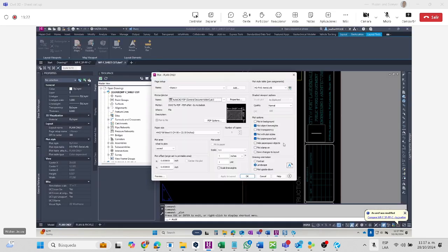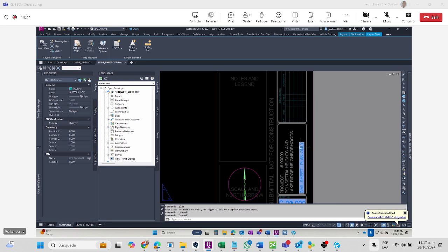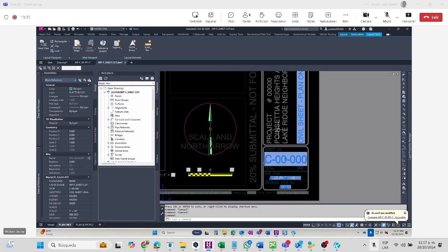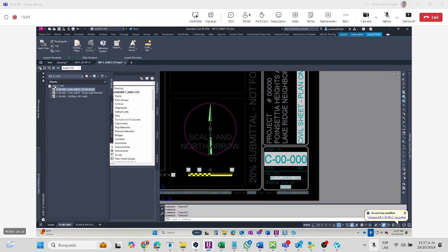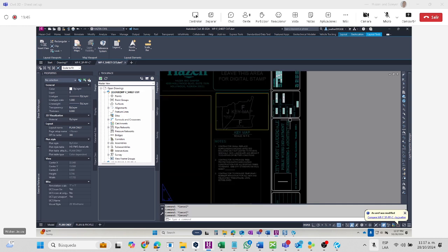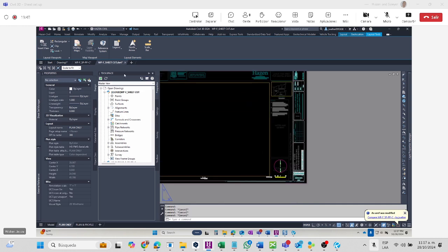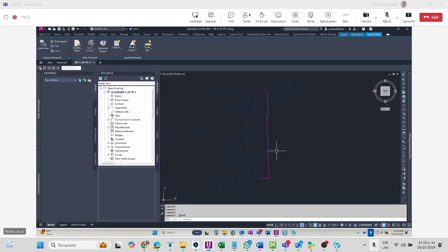Okay, and I was going to go through this attribute block, which is a little bit different. Their attribute block had a lot more information in it, and I wanted to simplify what we're shown on this drawing package and make universal changes without having to use too many fields of the sheet set. So I kept the sheet set fields to a minimum on this one. So basically that's what the template contains, and it's just saved as a DWT file.